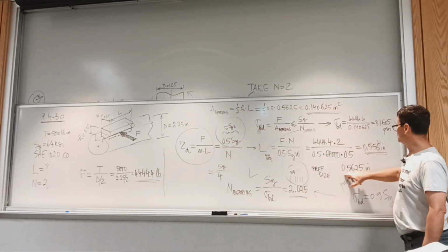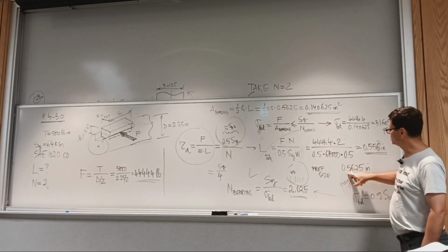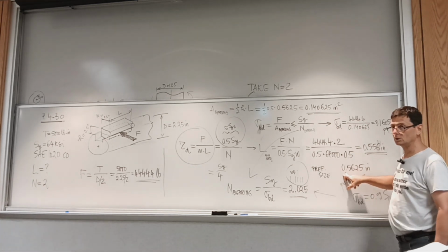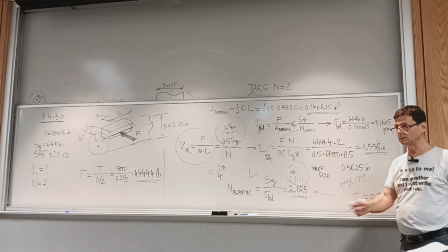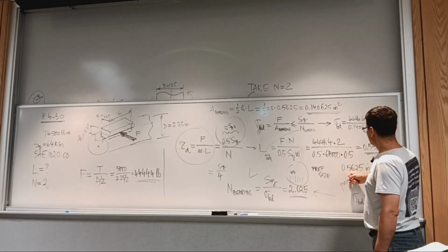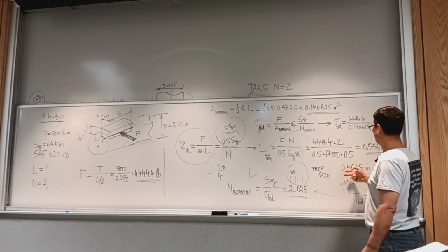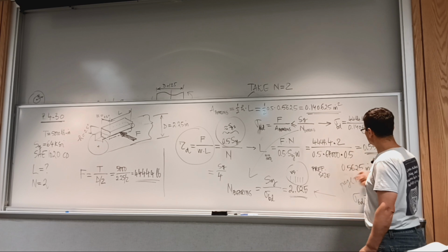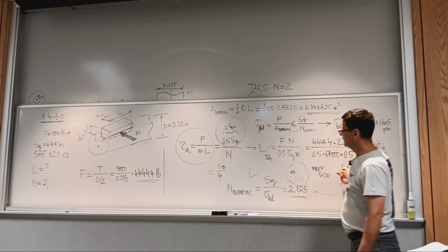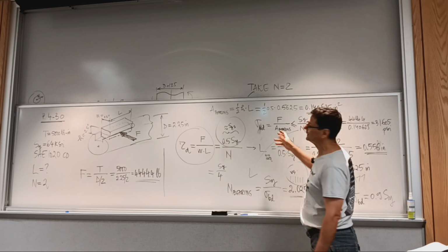And we round it to the closest preferred size, but I commented that even then it's too small. You don't want a key that looks like a cube, like a die. So other than increasing it slightly, and we stuck with that preferred size value, we then calculate the bearing stress.